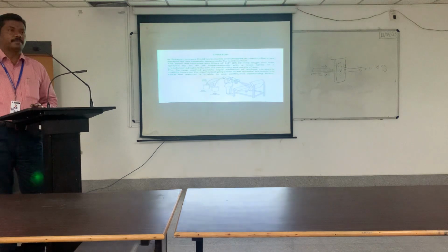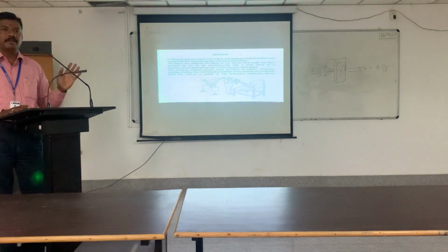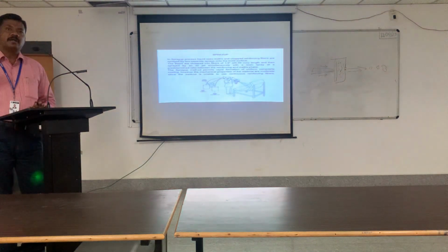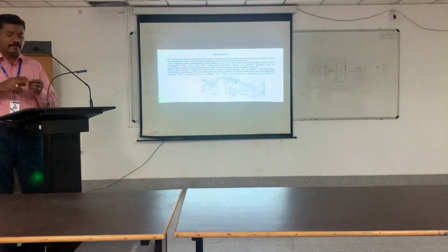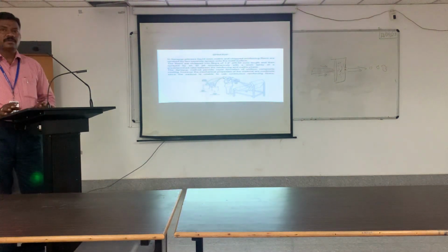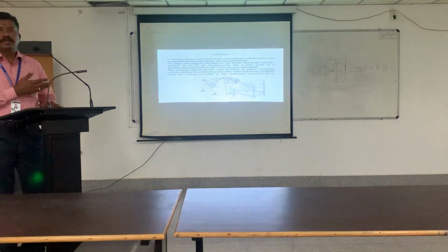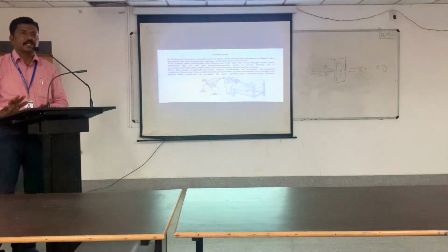However, in painting only the liquid alone will be there. In polymeric composite manufacturing, along with the liquid matrix material, fibers should be cut into smaller pieces and mixed. You cannot use long fibers here.